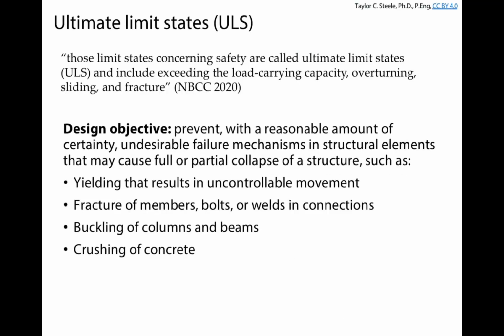Ultimate limit states are basically the limit states concerned with safety, and we're going to call them ultimate for no other better reason than, well, I don't know, ultimate limit state sounds cool, I guess. Basically, it includes anything where we're exceeding the load carrying capacity of a member, there's overturning or sliding or fracture of any particular components. What it means for us is we're going to want to prevent yielding that results in uncontrollable movement. We're going to want to prevent fracture of members or bolts or welds that connect everything together.